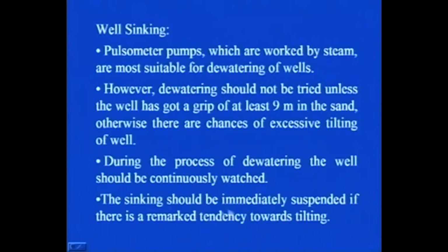The sinking should be immediately suspended if there is a marked tendency towards tilting. So in sinking, it is an important thing that the tilting should not be more than the permissible limit. Wherever you see that the tilting is becoming more, you have to stop the sinking. First you have to rectify that tilt and only then proceed for further sinking of the well.